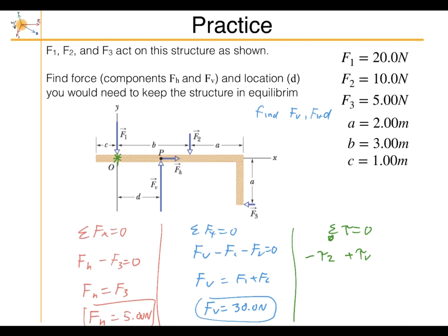And there's also a torque due to 3, which is also trying to turn it clockwise. So T3 is equal to 0. The nice thing about torque 3 is, to make it easier, we can just consider F3 and D3 perpendicular, which is just equal to A. Instead of trying to find this distance here, it's easier to just consider the perpendicular component of the distance.